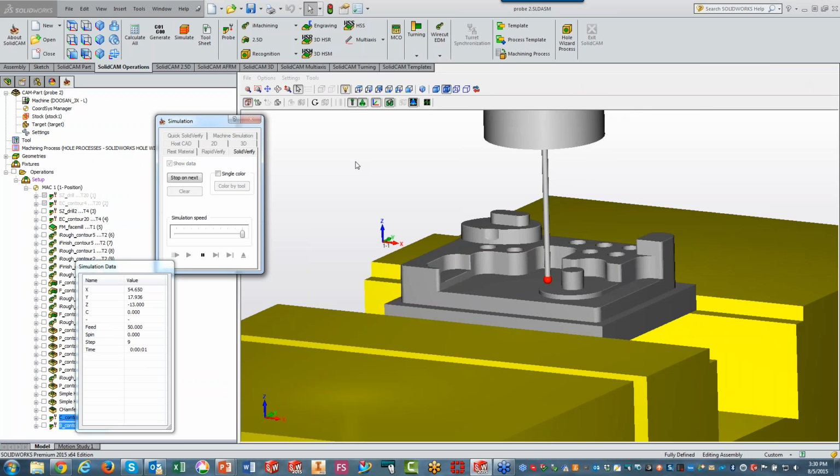You can see it going now and measuring around the part, the X and the Y, as shown over here. This is what this particular machine supports, this controller supports. And that's how it's done simply on the machine itself, without needing to take the part off the machine.